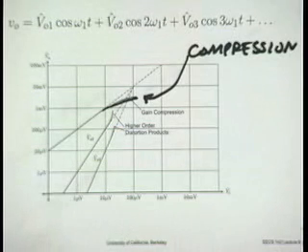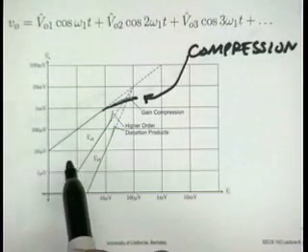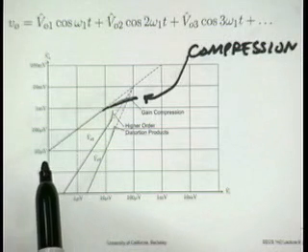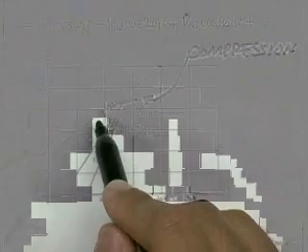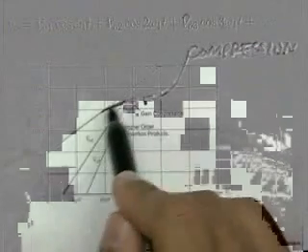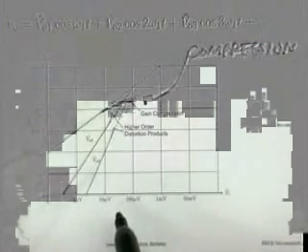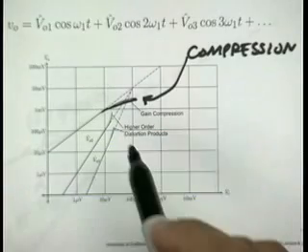Very good. Remember, we found that for very small signals, the fundamental is essentially generated by the linear term, A1. But remember, we looked at the cubic term, A3, and we found that A3 also produces fundamental. In fact, what we showed was any odd power will produce fundamental. And depending on the sign of A3, A5, A7, and so on and so forth, that might be subtractive. And so here, I'm assuming that it is subtractive, and so it's compressing the gain. So the gain's going down for large signal input. Okay? Same thing happens here.